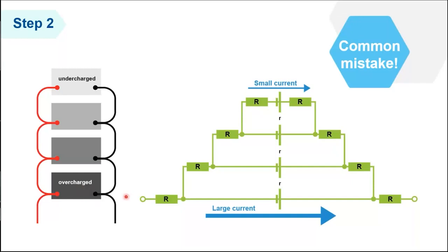And why is cable resistance important when wiring the batteries? Because the longer the cable, the higher the resistance. Also, the cable lugs and the battery connections will add to this resistance, and the resistance is not too much. I know it's about 1.3, 1.7 based on the material of the cable that you choose, but it has a significant effect. And the current will always choose the path with the least resistance. So the current coming here, of course, is lower than the current coming here, and of course the voltage. So the batteries will be unbalanced soon, and they will fail. This battery will start failing very prematurely.